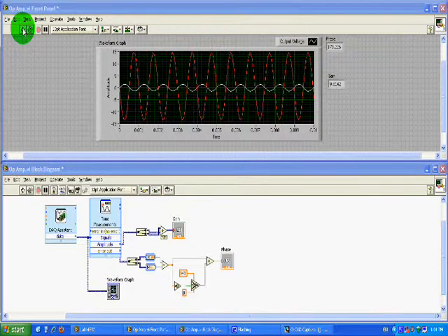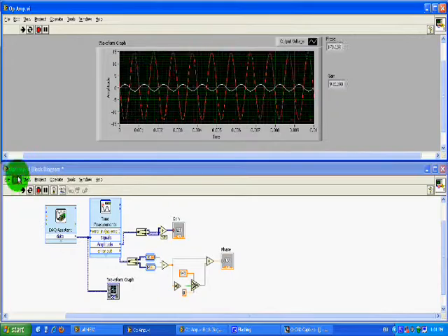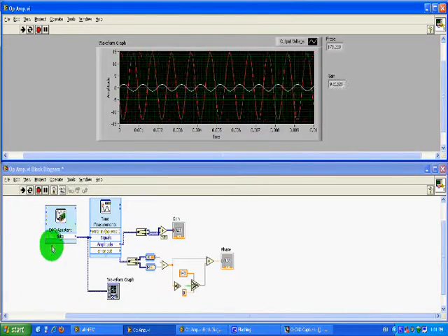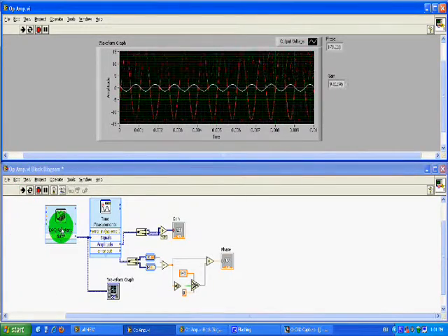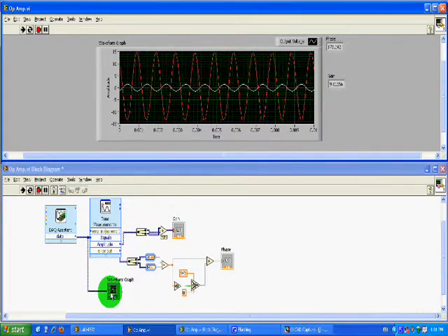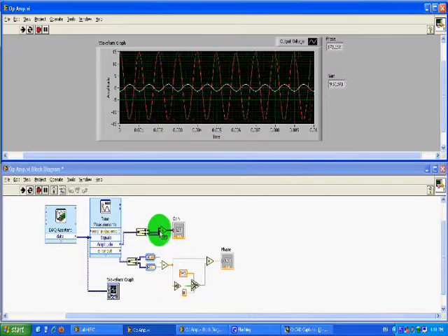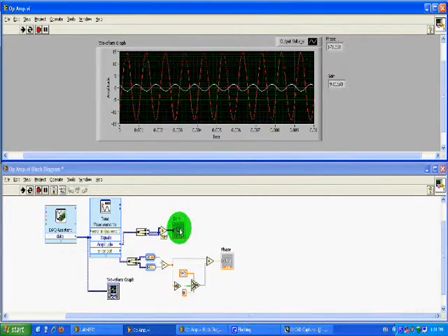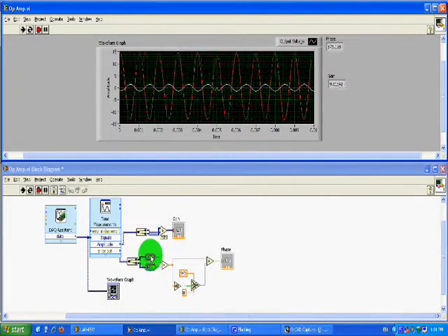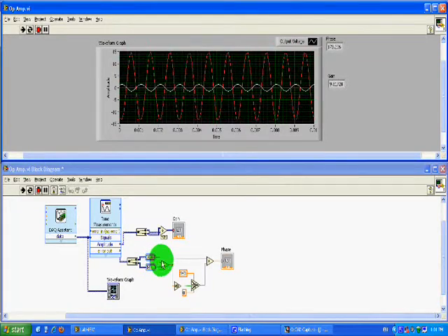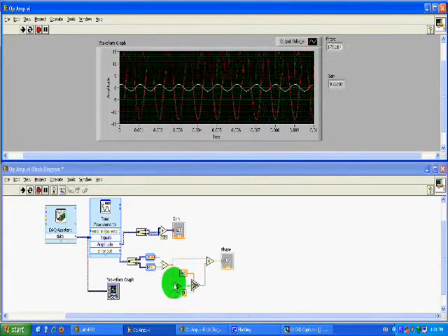This is our VI of our op amp, and we'll run the simulation continuously. We start out with the DAQ assistant, where it measures the inverting input and the output. We then put that in the waveform graph, and we measure the amplitude, and we divide the output by the input to get the gain. And then we use the phases to calculate the phase difference.